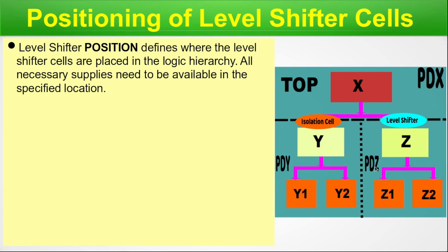Inside PDZ we have sub blocks Z1, Z2, but in that case we are not using any level shifter. Even for PDY we have different blocks Y1, Y2, and there we are not using a level shifter. We are using level shifters at the boundary only. That means with PDX versus PDY, the entire supply voltage is different. PDX, the VDD is different, and PDZ, the VDD is different. Similarly, PDY, the VDD is different from PDZ and PDX. The VDD supply for the X, Y and Z domains are different from each other.